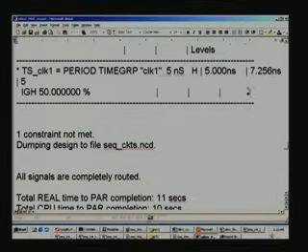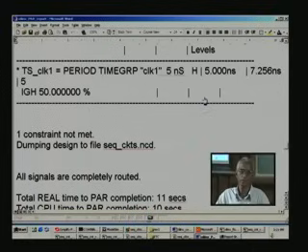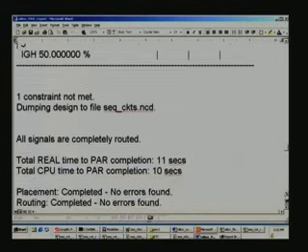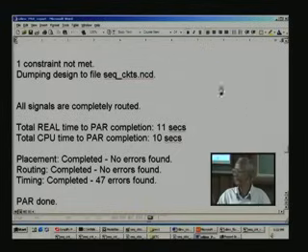And even here, in real practice, people have reported a bettering of the report Xilinx's place and route gives. For example, it may be 10 to 25% better performance that you can get based on real experience. So what they give is a guaranteed speed of operation here. And normally, as I mentioned, if the design is quite huge, what synthesis will report will be a much higher frequency of operation than the place and route.